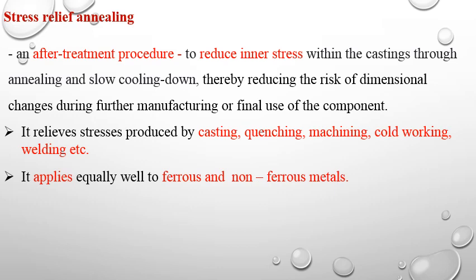The next one is stress relief annealing. It is used as an after-treatment to relieve internal stress within the cast during further manufacturing. It relieves the stress produced by casting, forging, machining, and cold work. It applies equally well to ferrous and non-ferrous metals.